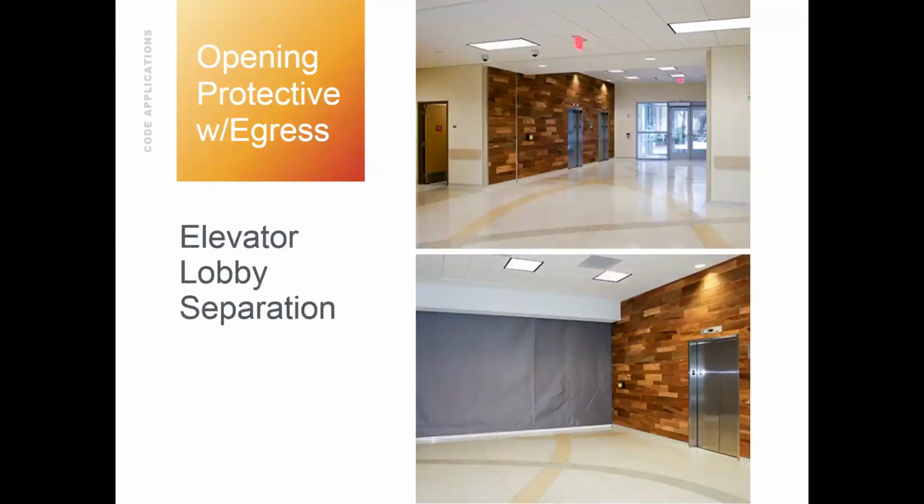But then the elevator lobby route, typically when you see buildings, depending on your occupancy classification, the occupant on the floor plate, greater than 3 stories in schools and such, we were just dealing with one of these. You have to create elevator lobbies, which is the common route. 1 hour fire barrier construction. This elevator lobby, they were able to utilize the curtain itself to create that separation, 20-minute rating, same kind of unit. But obviously you can see egress out of the building, which right as you get out of the elevator, it's trying to create that passive protection of the elevator lobby itself.